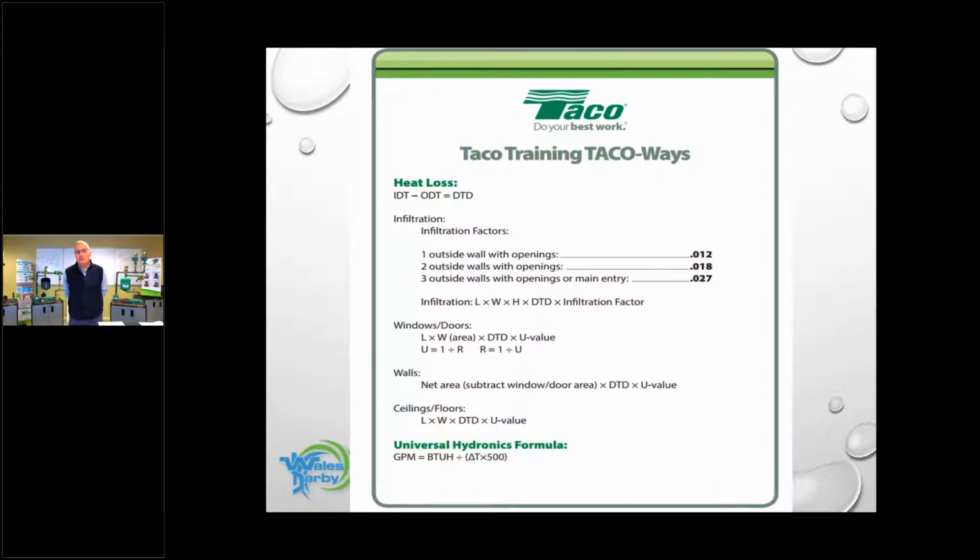That would be kind of standard for today's construction. If you've got 2 by 6 walls, we generally have an R19 in there. It could be higher if they spray foam with 1 inch and then back it up with pink insulation. We can get into R values of 25 and higher. If they spray the whole cavity, that R value can be well into the 30s, maybe in the 40s. So we need to know that. So for today's example, we're going to use 19.